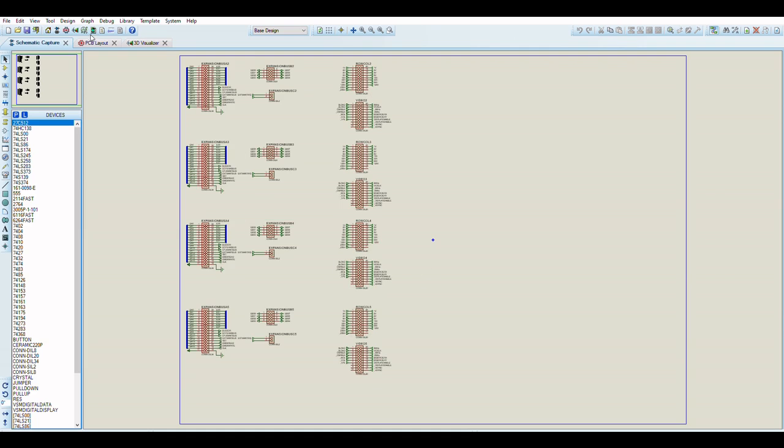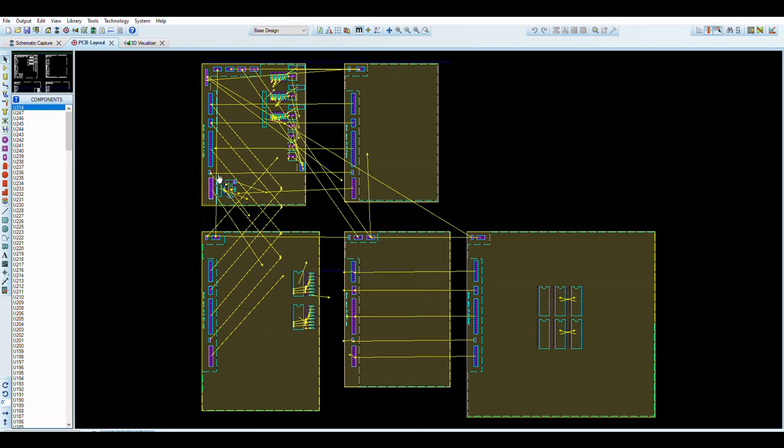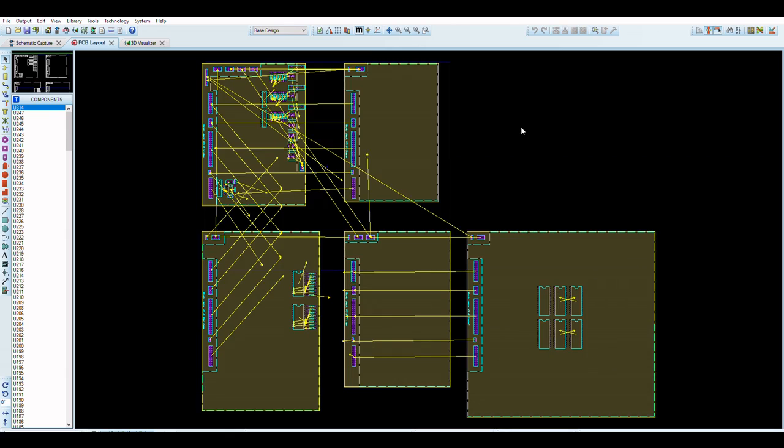So all of these, when you look on the PCB layout, if I turn off the rat's nest view temporarily to make it easier to see, these are the standard memory bus headers on each of the boards. This is copy-pasted in terms of layout to all of the other boards too, to make it easier for me to stack the boards or to interface the boards consistently.